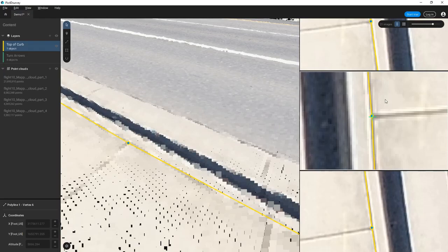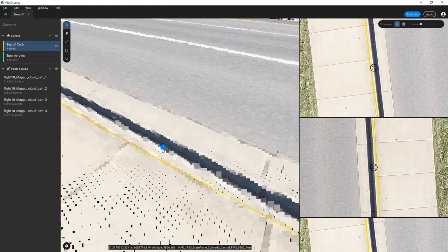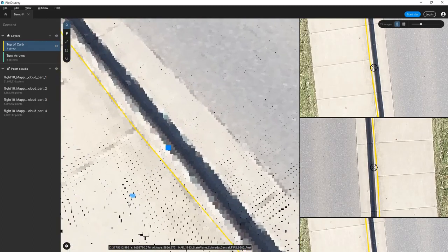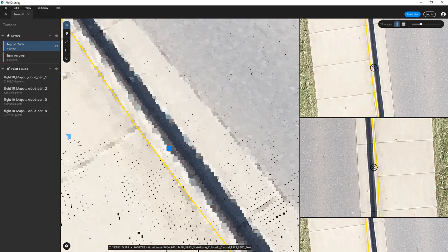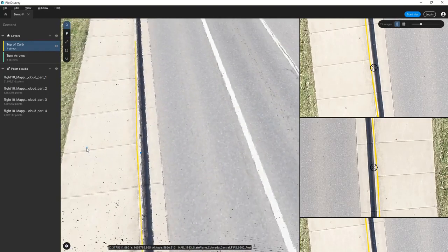Now, you have to remember you're doing all these edits, but when you work in the 2D, they're reflected in 3D, but they're never going to go back to your mapper project. You should only be working in Survey once you've finished the work you want to do in mapper. Any edits to the point cloud or anything that you do on the creation side, like back in step 2 in mapper, is going to mess with your results here. So that's kind of the basics of the creation and editing that you can do. So I hope that's kind of useful.